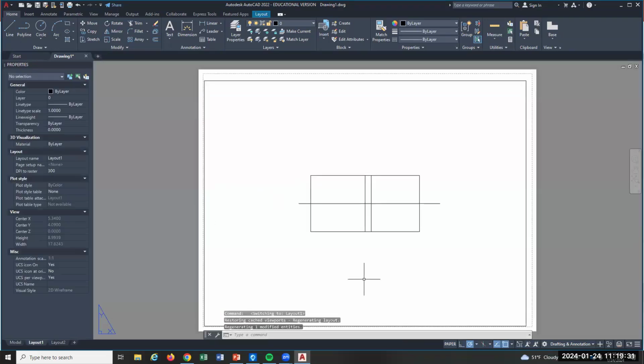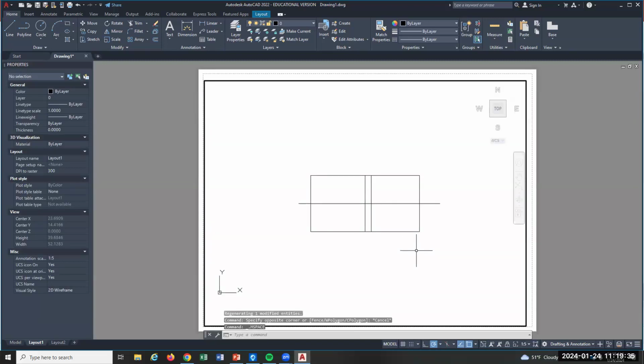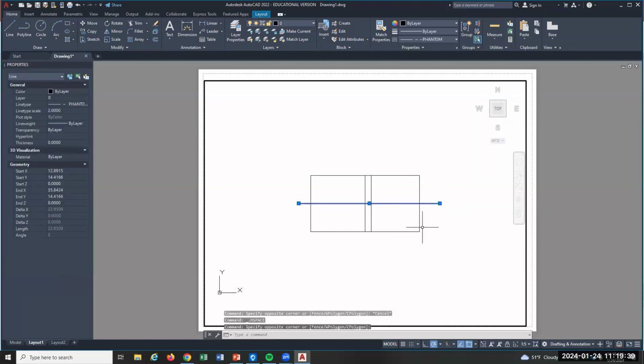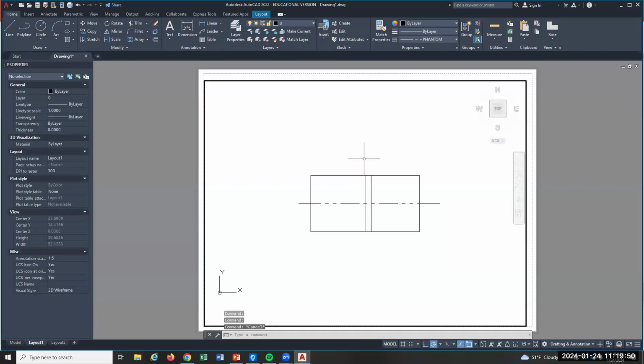This is where you want to look at it here, because if it looks bad here, it looks bad when you do the PDF, right? So tweak it here. 2 is not working. I'd go to 1. 1's starting to work. I'd probably want at least 2 of those to show up, something like that. Again, up to you, but it looks different in layout than it does in model. So do it in layout and be happy here.